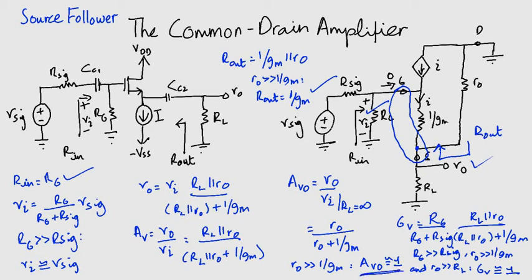It finds application in situations in which we need to connect a voltage signal source that is providing a signal of reasonable magnitude but has a very high internal resistance to a much smaller load resistance. That is as a unity gain voltage buffer amplifier.